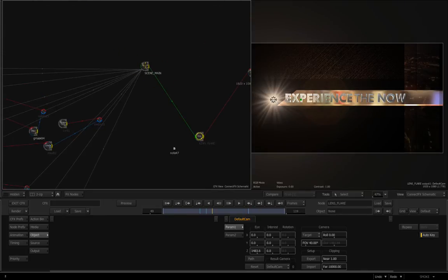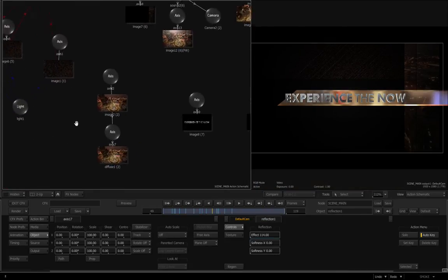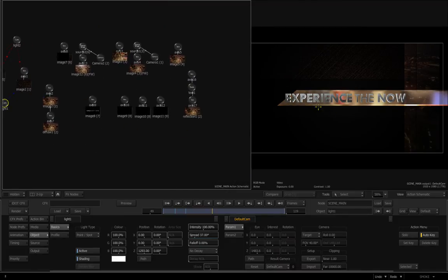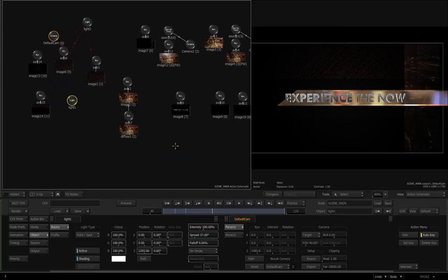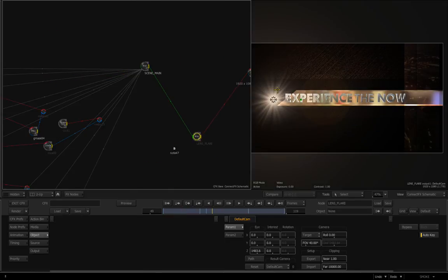Now, why did I build this outside in this action? Why didn't I put the lens flare inside here with the main scene? Well, to be honest, I was creating this and building it and didn't know I wanted the lens flare at the time. If you look inside the main action, I have lights set up for the scene, lighting various individual images. Once I would have added a lens flare, it would have altered the lighting because a new light would have been added, and I would have had to have made adjustments. By doing a lens flare external to action, I can keep my original lighting as is, and just supplement it with a lens flare on top of the entire scene. There's no right or wrong way to do it. It's just how I was working through the process in designing this effect.